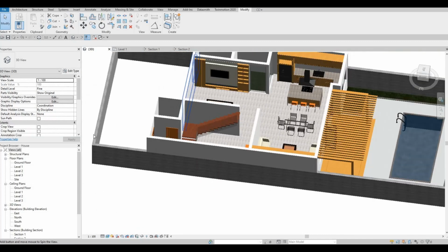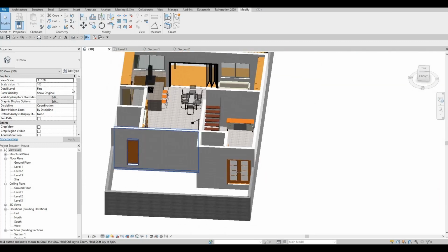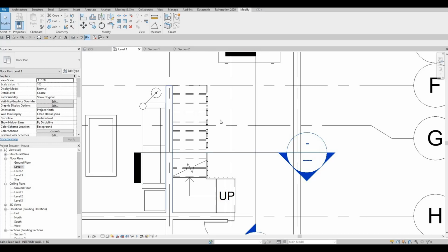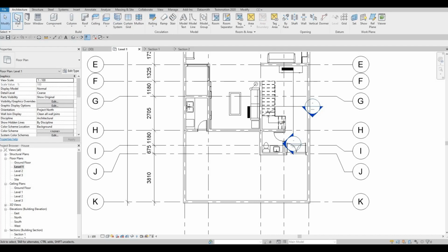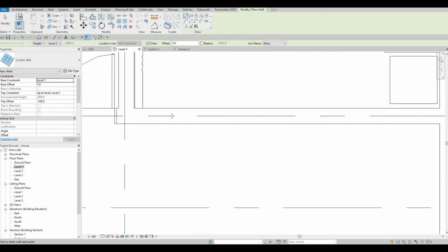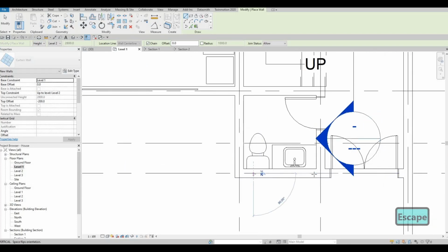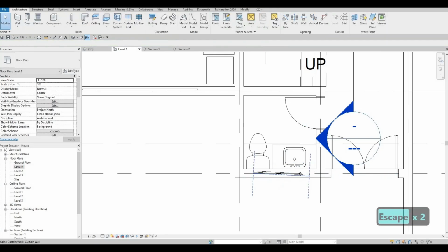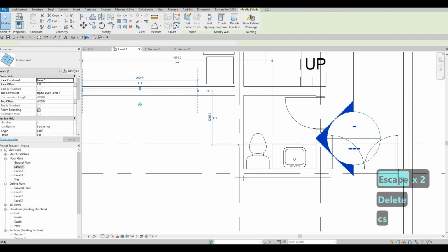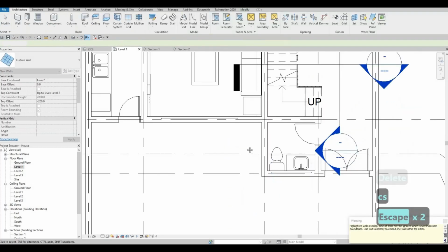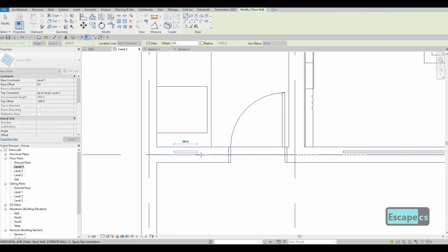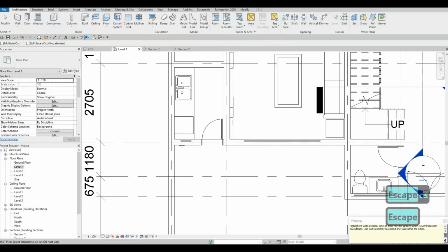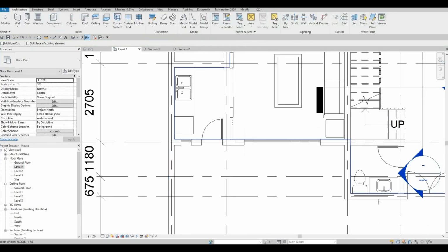And then let's do something right here. I want to add curtain wall. So windows right here. So we could do is add this one on this side, and then here at the top right here. And then I'm probably going to add here as well. So why not? Click on cut geometry, all first, and then curtain wall.